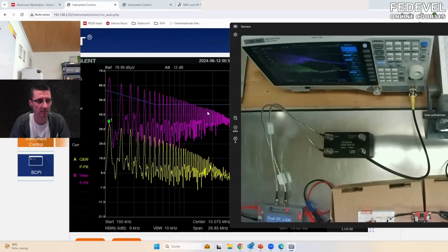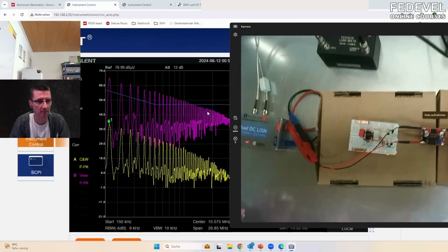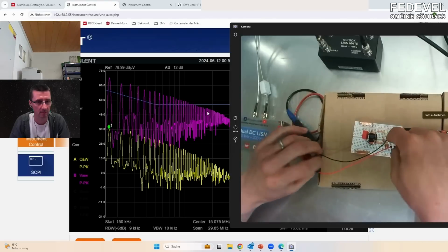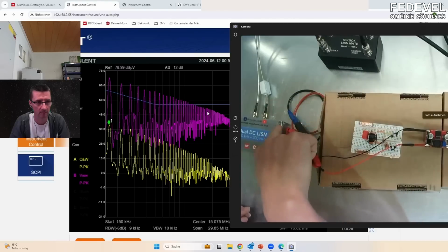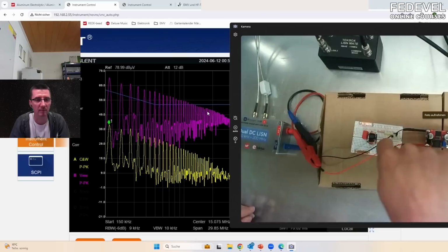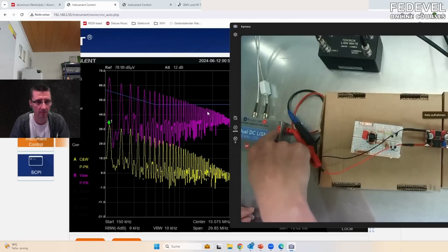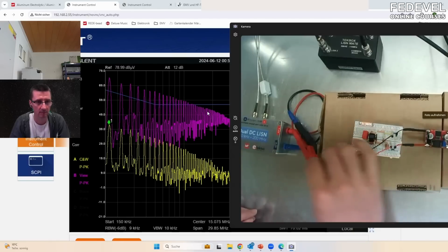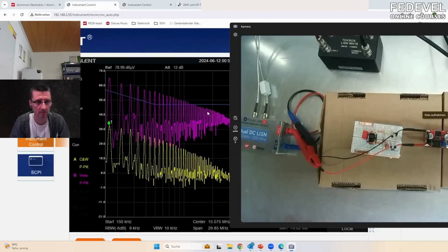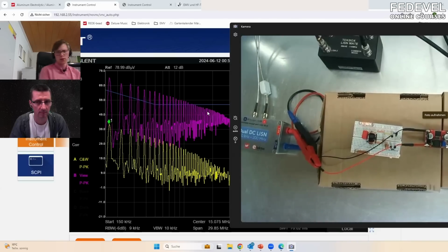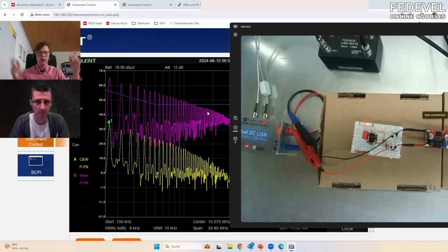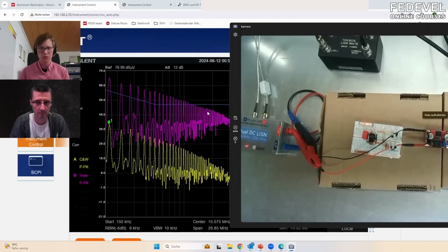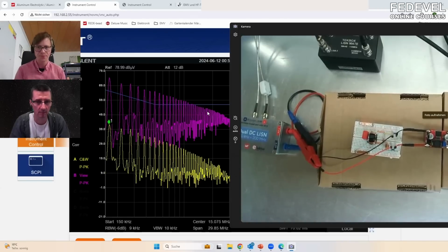So at the moment, going one step back, we have the problem that the current is going here to the load and then over the other line back. So we have this RF voltage drop between the lines. And especially when these lines are not close to each other, but spread like this, you will have an antenna, and this can also radiate.